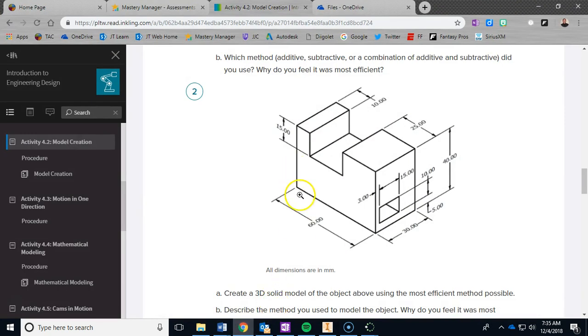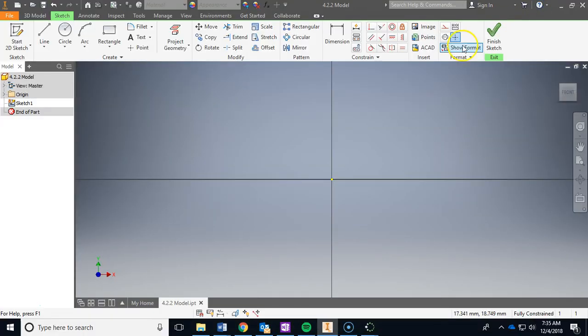So let's take a look. The front view, remember, longest dimension, most detail. So don't assume just because of the way this is orientated that it's automatically the front view. But it just so happens that, yes, this shape here is the front view. So I'm going to put this point right here as my 0, 0. I'm going to go over 60, up 40, over 25, and down 15. Let's start with that. So 60, 40, 25.